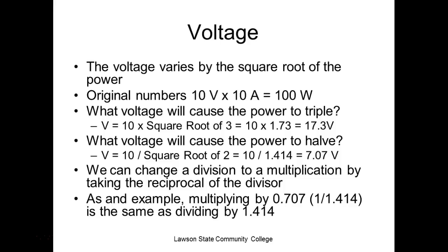So the range of frequencies down to 70.7% of my maximum voltage would be the half power point. But now we're doing the half power point relative to voltage and not relative to power, because to measure power, we have to measure two things: current and voltage. The power meter on the side of your house is measuring voltage and current. That's the RMS value for AC, but it's also the half power point. So we'll run into this 0.707 a lot.